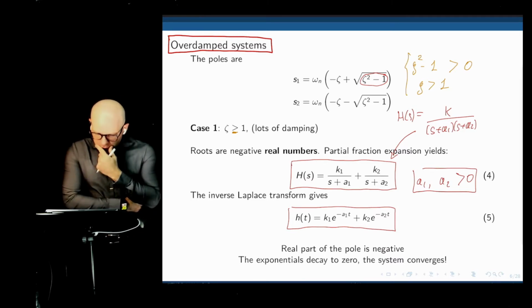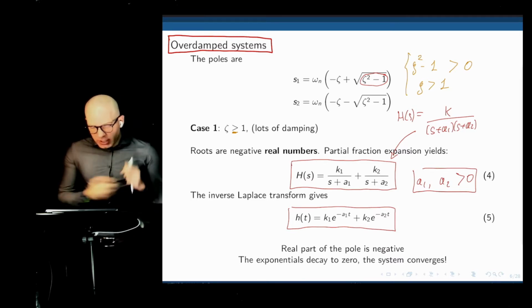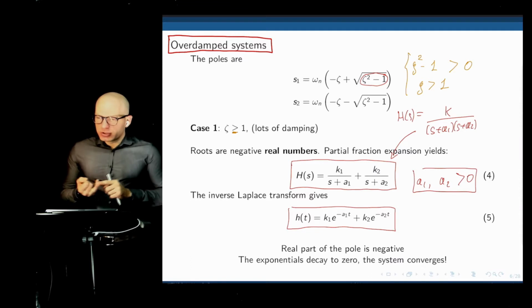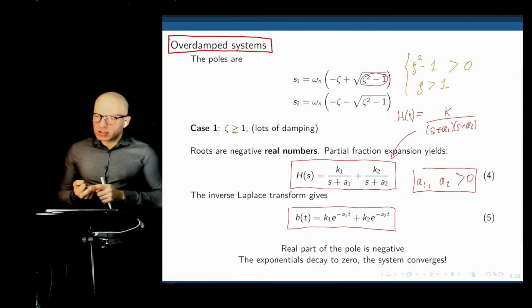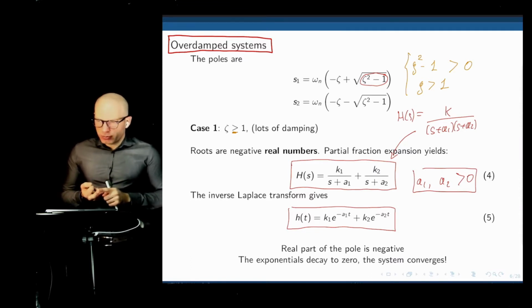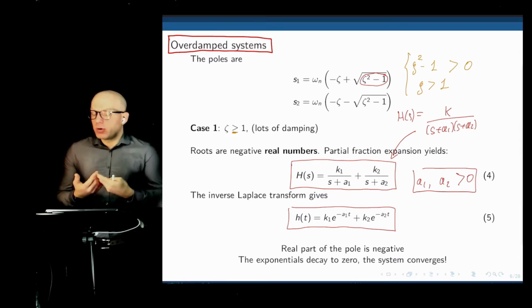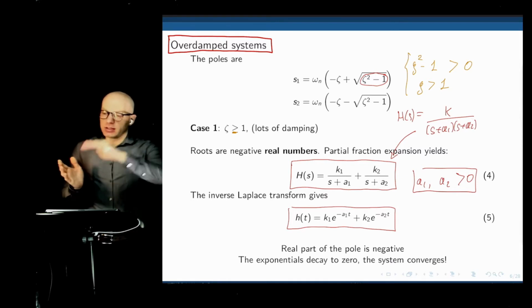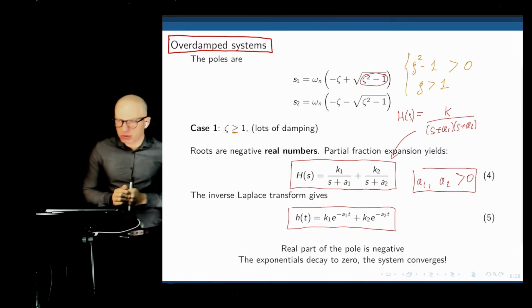What can we conclude here? We can conclude that we have no imaginary components in the time response. We have two poles. Each pole is real. Each pole generates its own exponential. No sinusoidal component. The system is overdamped. It will behave as a first order system in the sense that its time response is an exponential component.